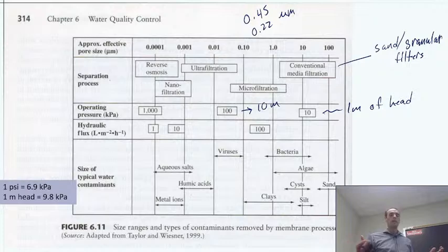microfiltration, a typical microfilter membrane would give us about 100 liters per square meter of the membrane area per hour. So in that sense, we can imagine, okay, we have 1 square meter of membrane, we give it 1 hour, we produce 100 liters. Okay. Then if we take that from a microfiltration system down to a nanofiltration system, that is now just 10 liters. We can go all the way down to a reverse osmosis membrane, and that's 1 liter for that hour.